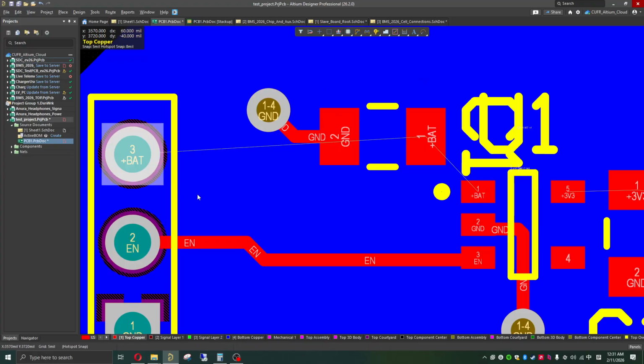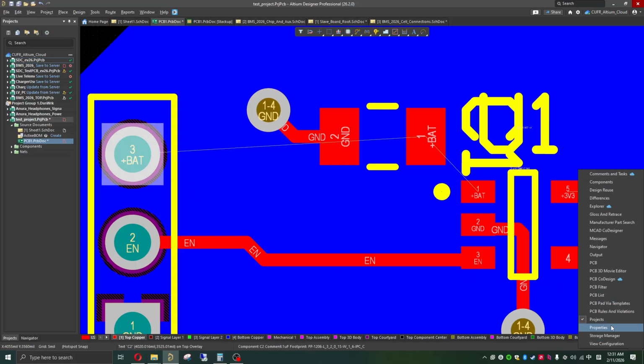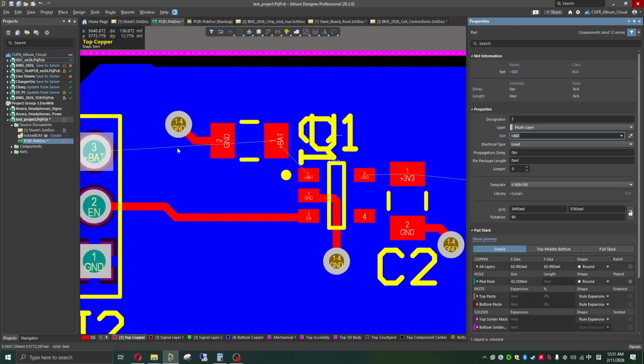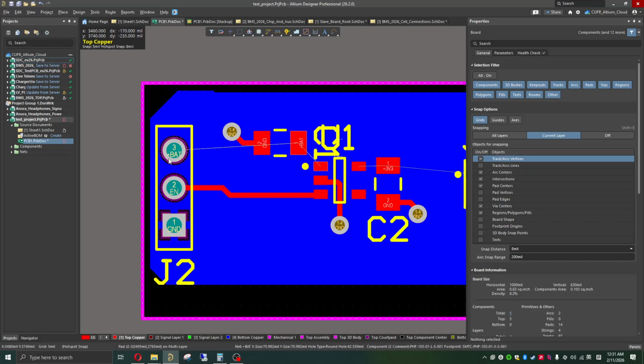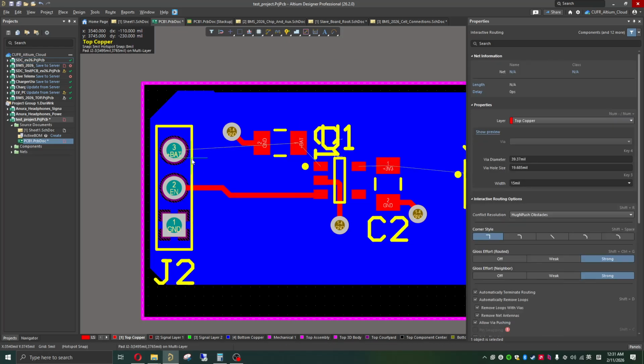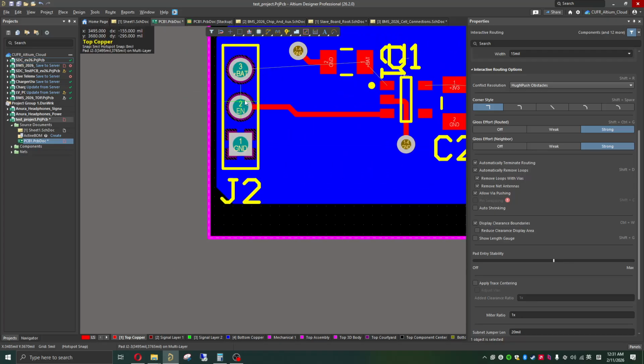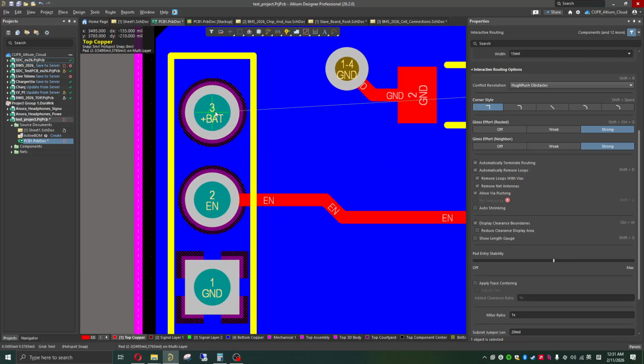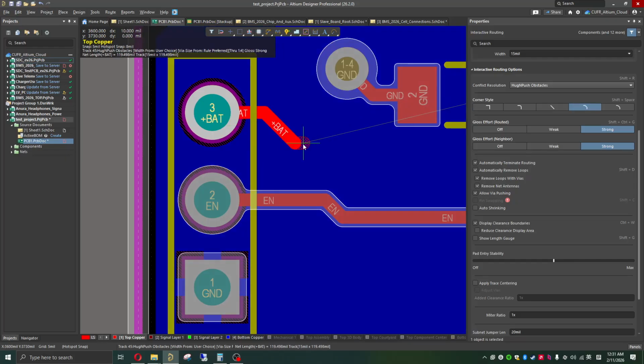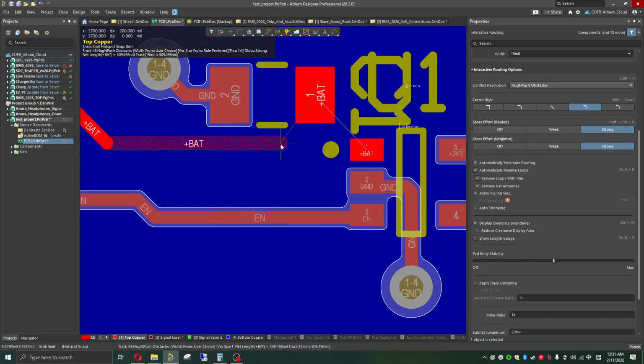I'm not too sure what the project specs are, but what I want to do is go to panels, and go to properties, and then in the empty space I'm going to press Ctrl W, and I'm going to get a bunch of different options for how I want to create this trace. Oops, sorry. So what I'm going to do first is create this connection, and connect to the battery. You'll see that stuff that is not the same node is going to be highlighted in white, or maybe another color depending on what options you have.